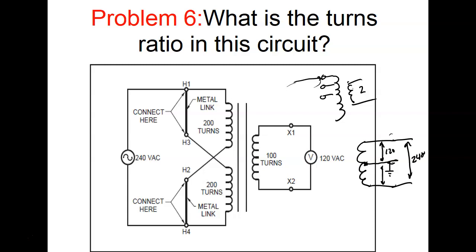Anybody know why we want to ground these metal things? Because they're metal, and we're using AC. AC creates a change in magnetic field, and AC would induce a voltage into the metal. You understand that? So we had a guy come in and say, I'm outside, and it's been raining, and every time I touch my air conditioner, the metal on it shocks me. But what's he lost? He's lost his ground, right? Somehow the ground that's connected to that metal out there is gone.